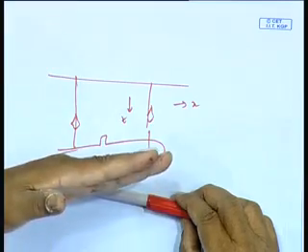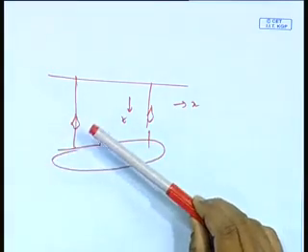I just rotate the model 90 degrees and oscillate, so I can get horizontal plane motion, because in deep water I can simply make this the horizontal plane by turning the body like that. So you see VPMM, what is called for submarines, where it is submerged, I can oscillate in a vertical mode, but this vertical direction can be made the x direction, y direction, by simply turning the model. So you can get both yv and zw and so on. That is what is called the vertical planar motion mechanism, applied for submerged bodies, whereas for surface bodies we use the horizontal planar motion mechanism, because my free surface has to be there. It has to be half submerged, you cannot deeply submerge it.